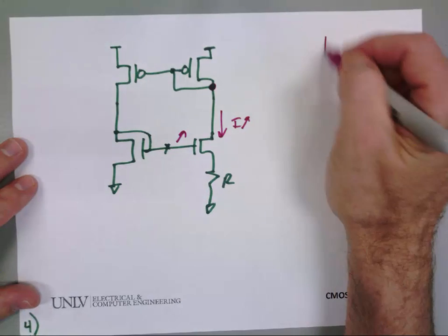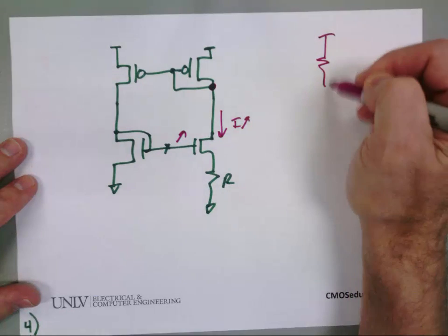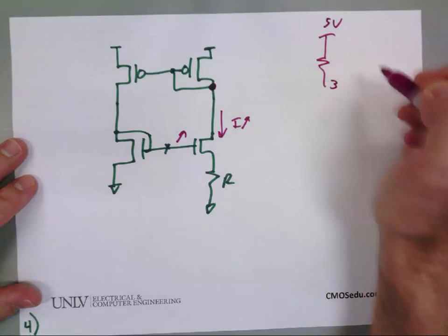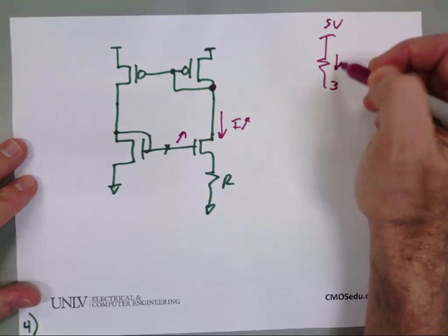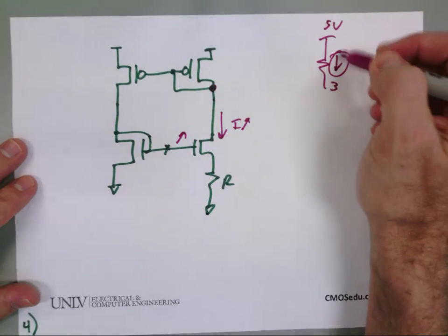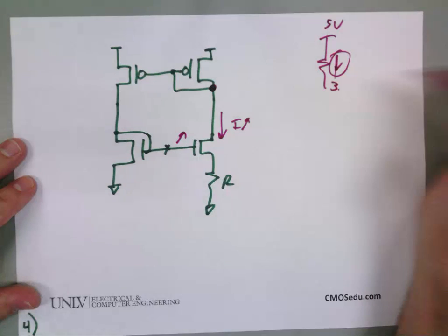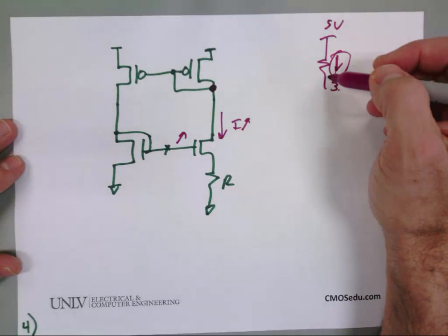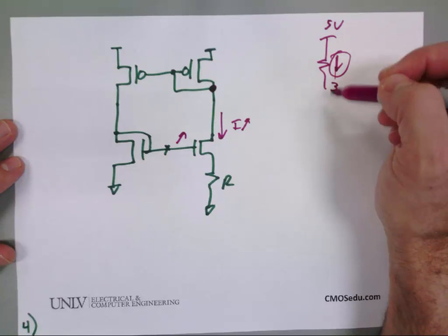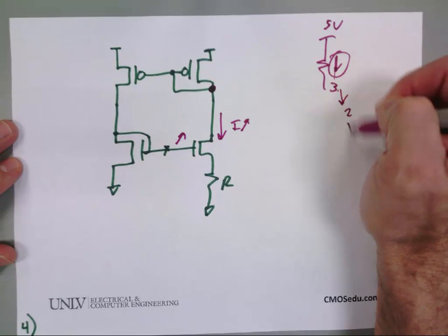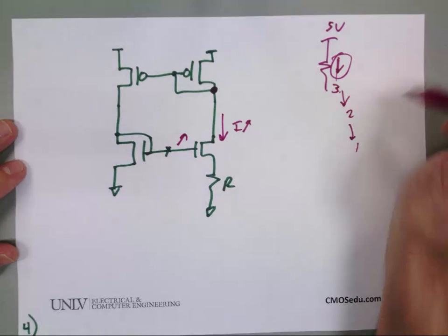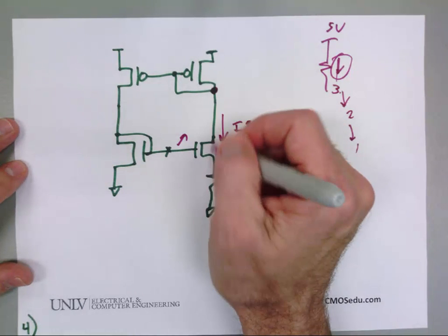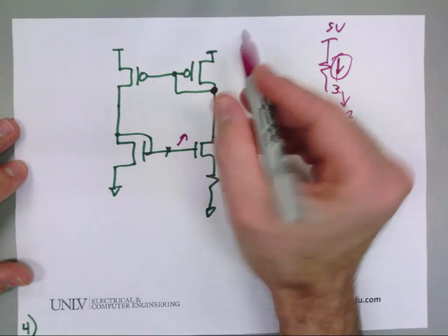So let me ask a simpler question. If I say this is 5 volts and this is 3 volts for some current that flows, and now I increase the current that flows through the resistor, what happens to that voltage? Drops, right? If I pull more water through a small pipe, I get a larger pressure drop. So this drops, say, to 2 or to 1 or whatever. Does everybody agree? So if I increase the water that's flowing in this pipe, what happens to the voltage here?